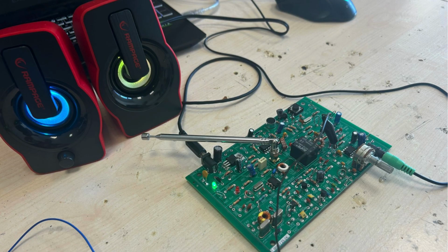Here is the TRC11 that is used to give the sound output to the speakers according to the square wave signal it takes from the BASYS3. I only used the speaker amplifier part of the TRC11 to turn digital binary signals to sound waves.